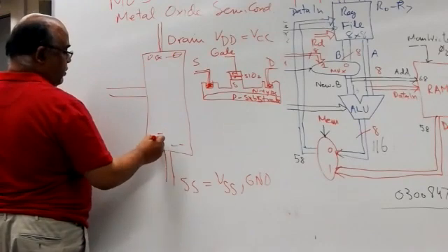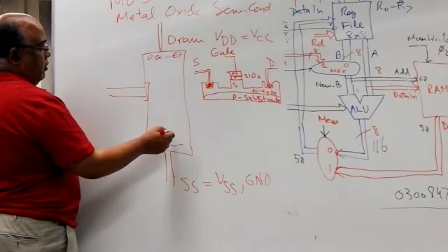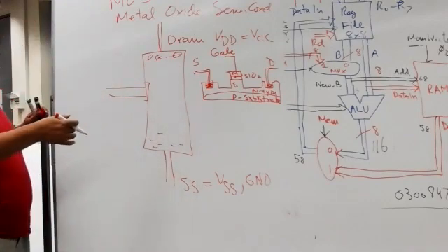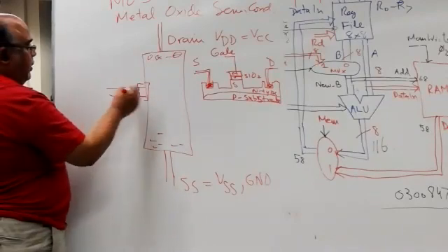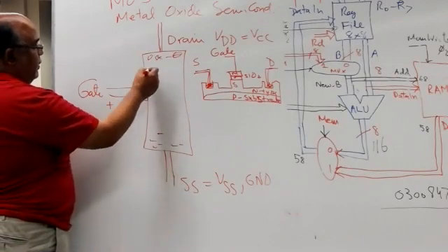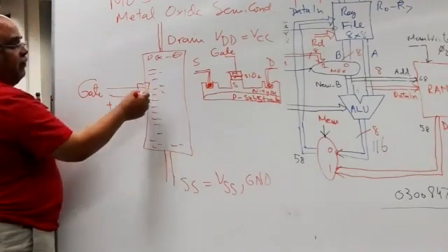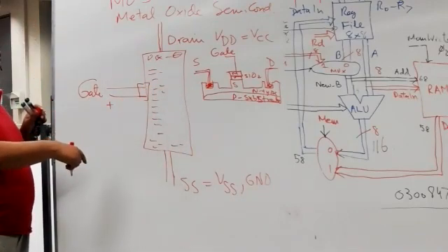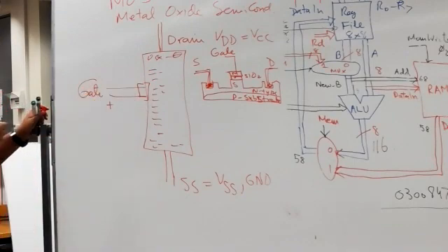They are gathered here, but there are no free electrons here, so that the current needs some free electrons to flow. So when we apply through this gate some positive voltage, that attracts these electrons. So when there are plenty of electrons connected between up and down, these are attracted here because of the static charge. They are not here because of anything. They are just here like a capacitor.